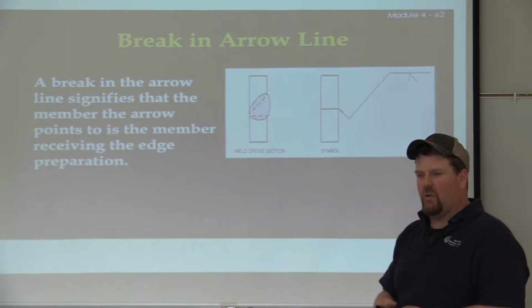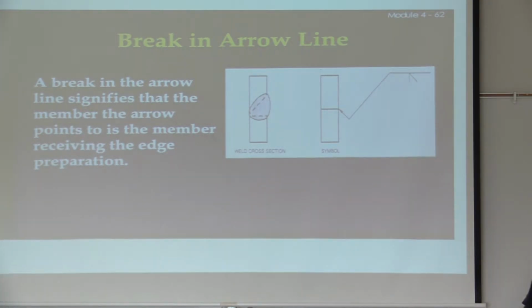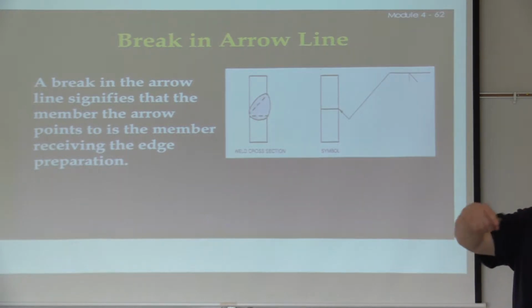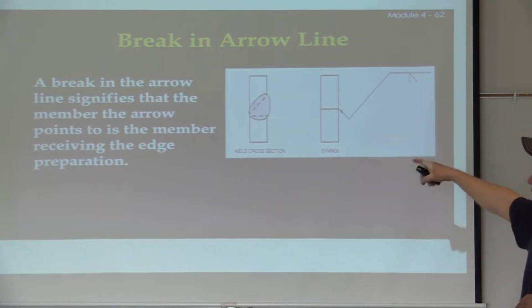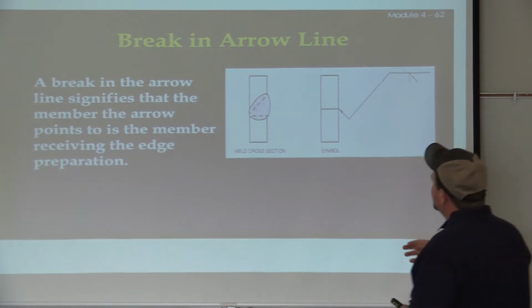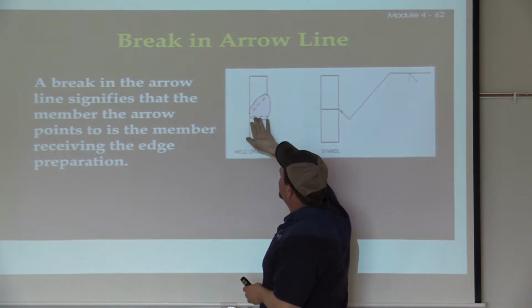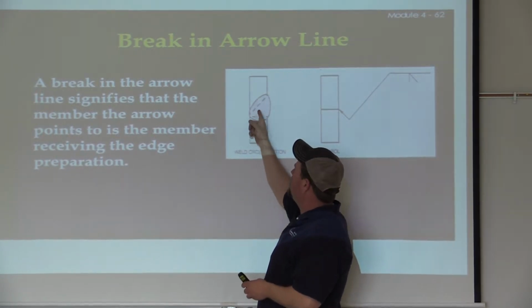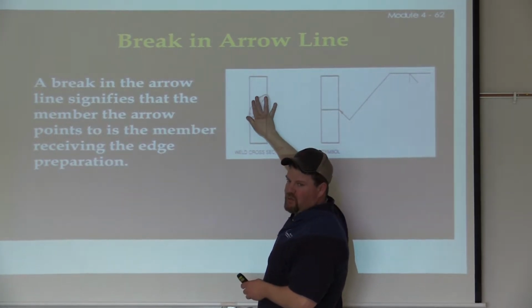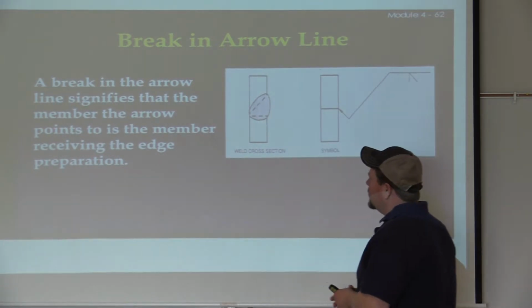So you're going to be doing a horizontal weld. But if you're putting a sheet of plate down like this, or say a pipe or box tubing around that, you're usually going to do the bevel on the top side, because gravity's going to pull it down here on the bottom, so you wouldn't want a lack of fusion going this way. You'd be trying to fight to get up here to get to this top edge. So this is working for the welder, with fewer discontinuities and so forth.